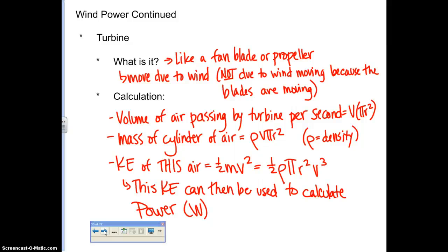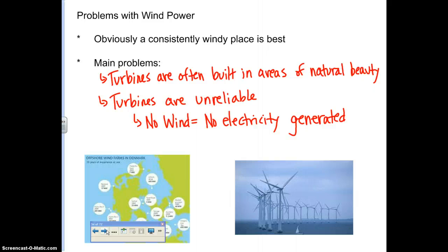Calculations, you've already seen one of these. The volume of the air passing by the turbine per second will give you the mass of the cylinder of air, which then lets you calculate the kinetic energy of this air, and also power eventually.